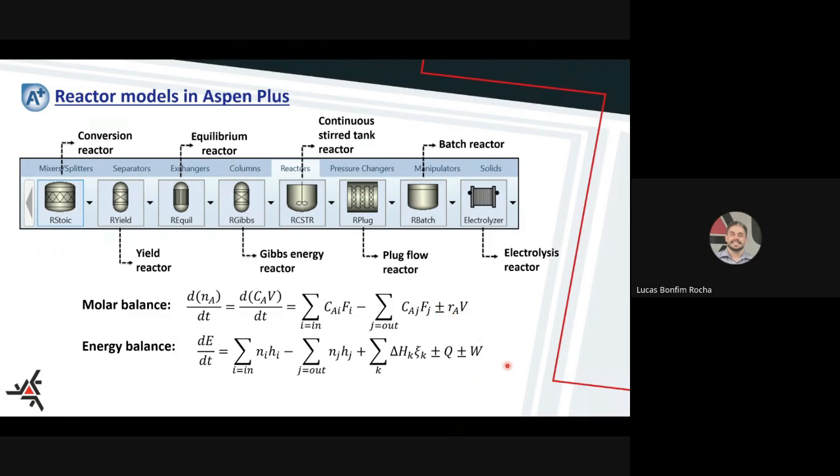Okay, so when we aim to simulate a reactor, we are trying to solve the molar and the energy balances for giving information about the composition of the products after the reactor, and also the energy required to keep the temperature constant if the reactor is isothermal, or also the amount of energy for keeping some value of temperature, or the heat of the reaction that was removed or was provided to the reactor for promoting that reaction. Okay, so we can solve these models for achieving all these results.